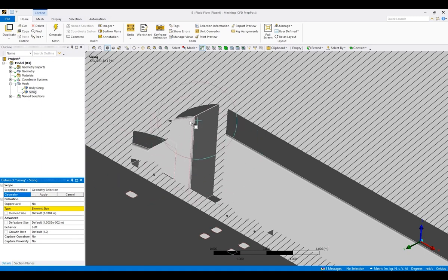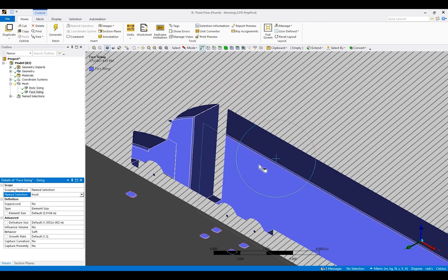And regarding the geometry here, we need to select all the surfaces of the truck, but as you all can probably remember, we had previously done that by giving names to different surfaces of the truck. So in front of the scoping method, all you have to do is to change it to name selection, and as for the name, you can simply then select truck. In this way, all the surfaces related to the truck would become selected without any effort.